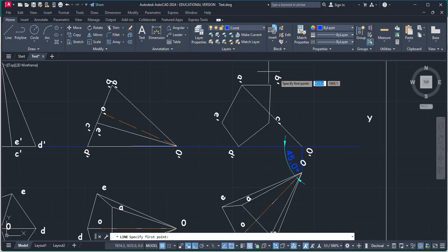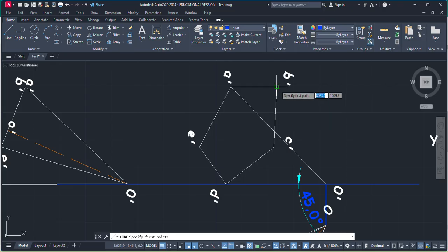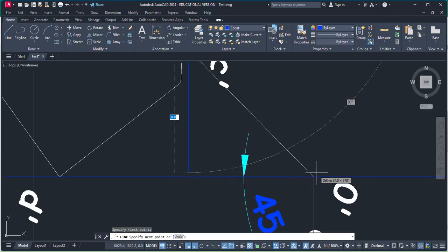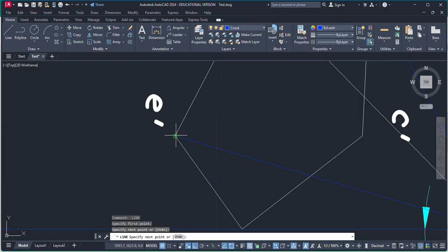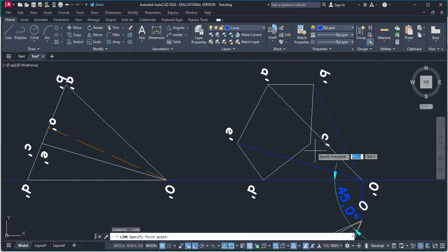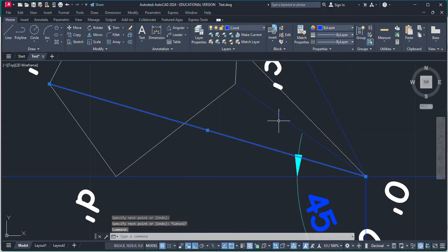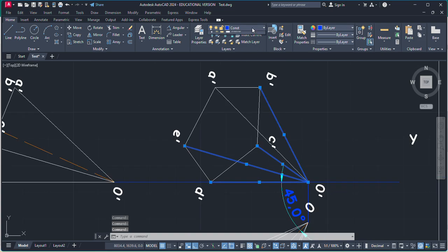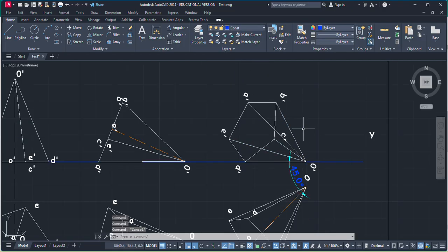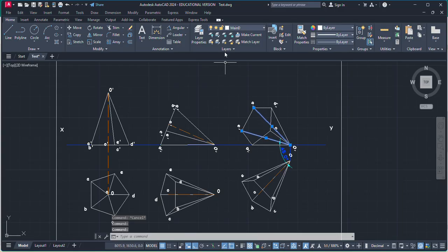Okay, now connect all corners to the top point so that we can get our slant edges. Again from here to here. So okay, this one is left. So these are our slant edges. Just change it to the main drawing. Now in the front view, these two will be invisible. So going to change these to the hidden lines.